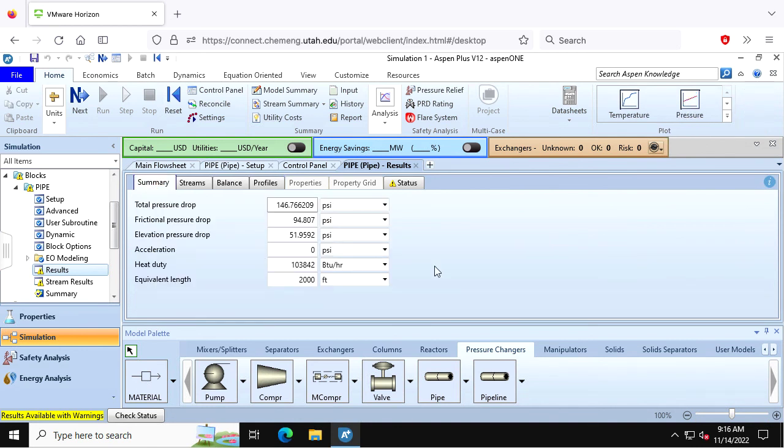Okay, and when I say learn a little bit of geometry, I don't know how to teach this. Please, when you take my class, know that the outer surface area of a pipe, we're doing heat exchangers, and I say, okay, what's the surface area of a pipe? What is the formula for the surface area of a pipe? Pi d L. Yes, pi d L. It is not pi r squared L. First of all, that gives you the wrong units, right?